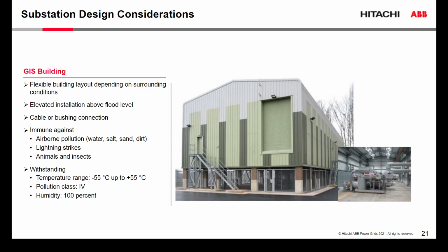If you have specific places where you want to get the substation above ground, close to the shore, that would be a typical installation where you would use such a building. Such a building actually eliminates the need for high voltage cable trenches and cable trays underneath the substation, where you can connect directly to a duct below the substation design.